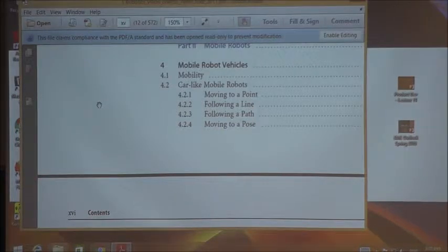So if you don't like the first error, keep repeating that and try to fine-tune your controller, play with some of the parameters of your control algorithm. If you have PD controller, look at the proportional and derivative gains. Do some investigation, do some trial and error thing. Hopefully you can keep improving on the odometry error. Okay. And do a video. I like to see the video. Yeah, they should take a video. We like to see a video of what you have done.